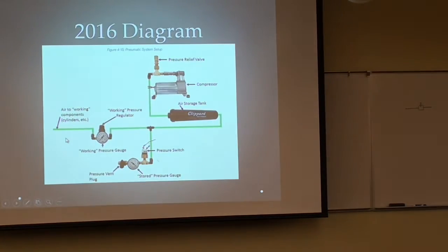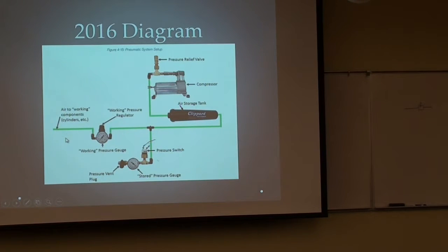So that's what it looks like. And so basically, you were asking that question, so you can see they've minimized the amount of hard piping coming out of the compressor. And then after that, even though this is all high pressure side, they did it with tubing, okay? You don't have to do the whole high pressure side in brass tubing. Only this connection from the pressure relief valve to the compressor. So this minimizes the lever arm that you've got, right?